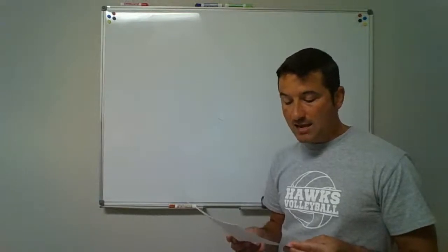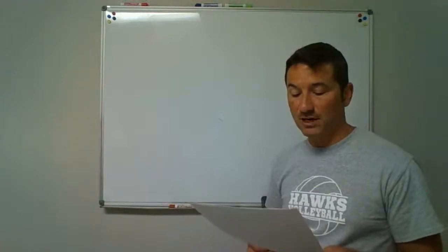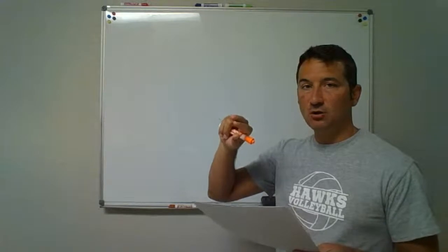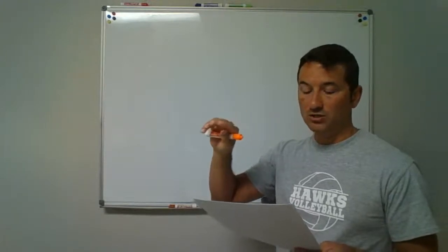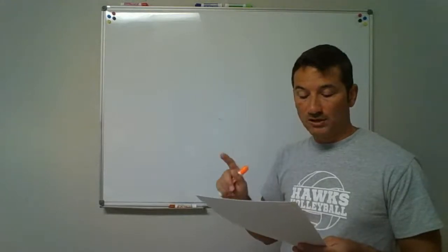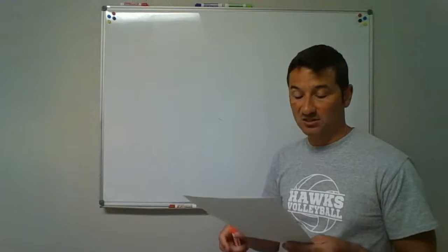Next question, number 8, is what's the maximum horizontal hanger spacing for CPVC pipe that's 1 inch or smaller? So there's two. Remember, look at the chart. One's for 1 inch or smaller. One is 1.25 inches and up. So the 1 inch and smaller is a 3 foot maximum, 36 inches maximum.